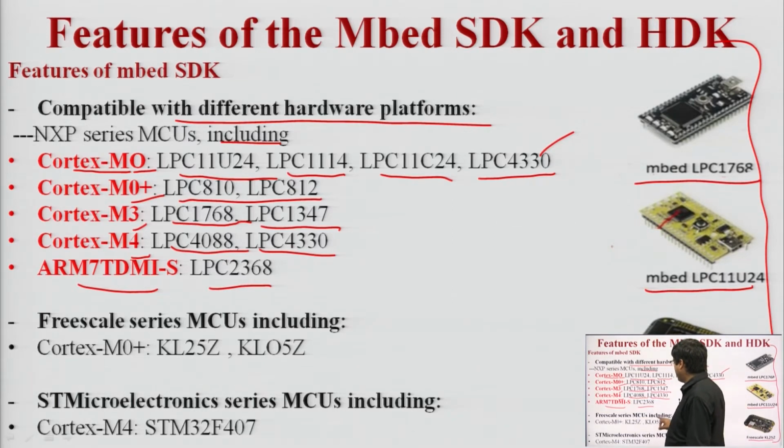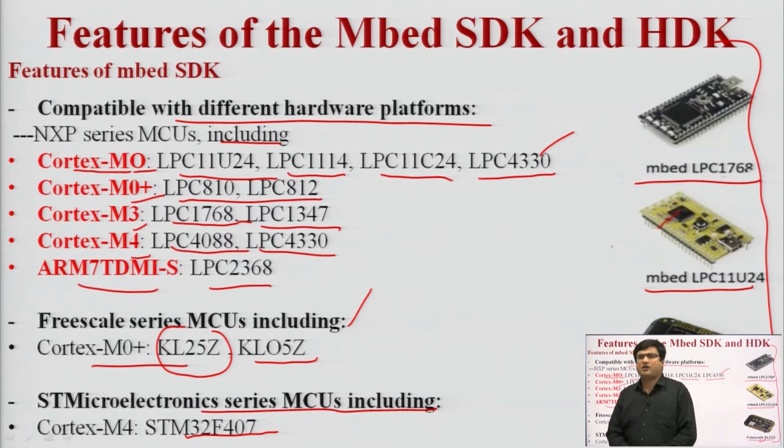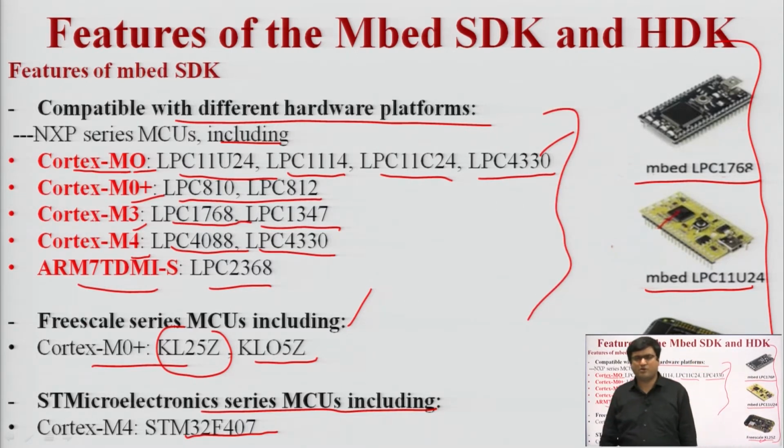Freescale series microcontrollers including ARM Cortex-M0 plus KL series, like here KL25Z, KL05Z, all are compatible with the Mbed. ST Microelectronics series microcontrollers including Cortex-M4 and STM32F407. So the code written in the Mbed is compatible with the different hardware platforms we have discussed here. Many ARM Cortex boards are compatible.